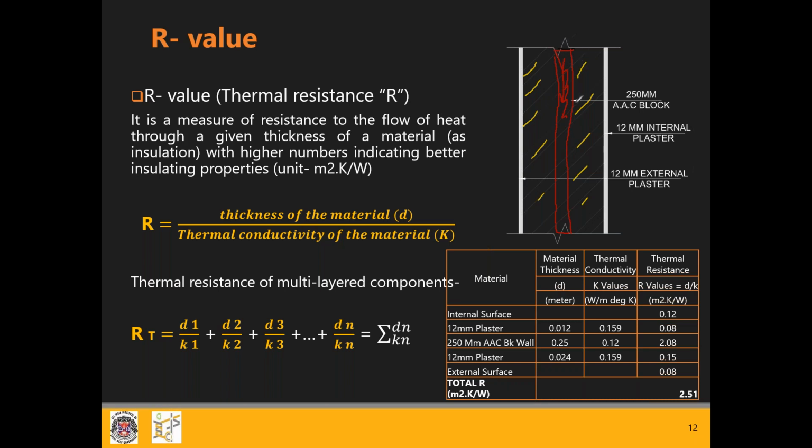So these are the ways you have to see which combination on my external wall or roof will give me the RT value that complies with ECBC. Of course, you need to factor in the cost implications as well. If you do not have that much budget, you have to see where I can trade that off. We'll come to that in the later section of the presentation.